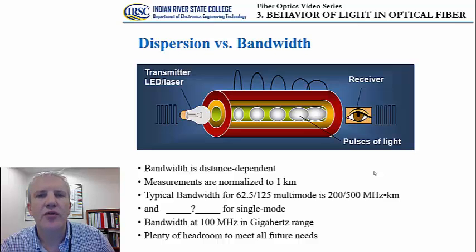And then we also dived into the concepts of attenuation and dispersion, two main causes of signal loss in the optical fiber. We have described attenuation and important causes that are associated with the attenuation, namely the scattering and absorption. We also talked a little bit about the bends. We classify them into macrobends and microbends.